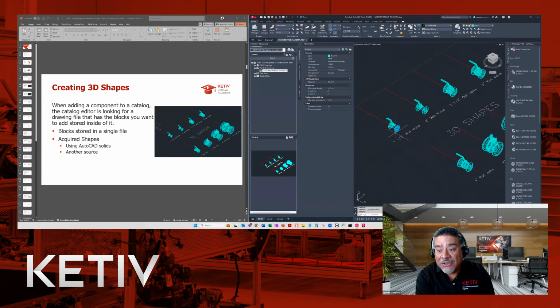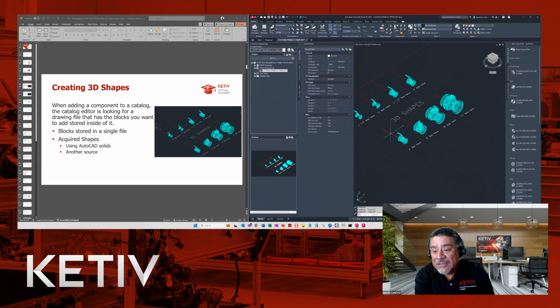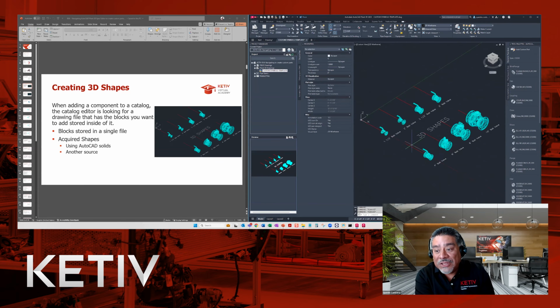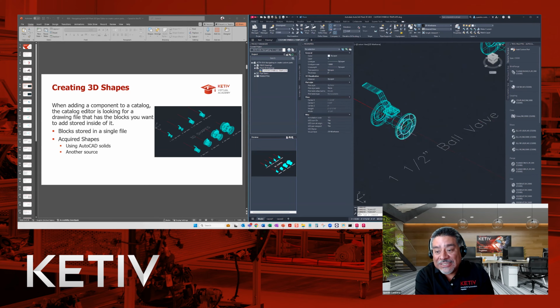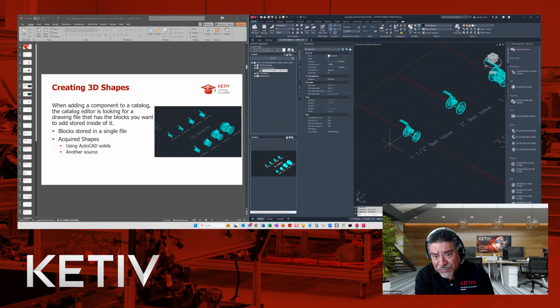So if I go through here, I can see that there are some items here that I need to add and so forth. And I can look at the properties here. I think, let me double check. These might have been exploded down all the way. But what you're really wanting is not surfaces here, like this one's a surface. What you're really wanting is a 3D solid of this, and that's what you're going to use to do the plant part convert.